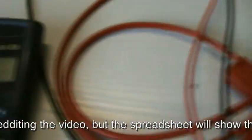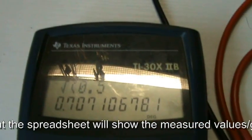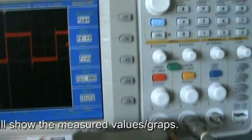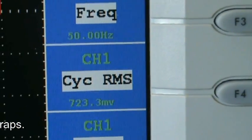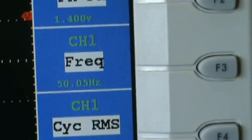So when we calculate the square root of this combination, 10 divided by 20 is half, and then if you calculate the root mean square voltage, it should be 0.707 volts. And that's also what is being shown here, almost, a little bit more. So this is reasonably comparable with the 50% that should be in theory.